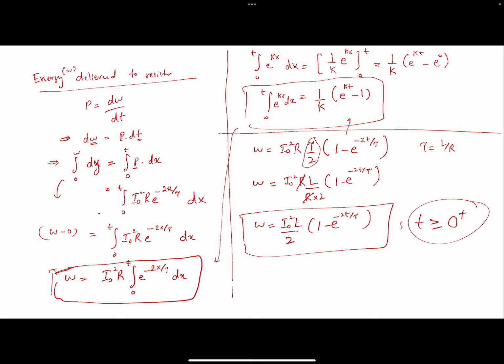And we just did the switching event at 0, and the inductor current cannot change instantaneously exactly at that instant. So that is why everything is valid for the resistor at t equals 0 positive, and for the inductor itself, the inductor current is valid for exactly t greater than or equal to 0 as well. Okay, so this is good, right?